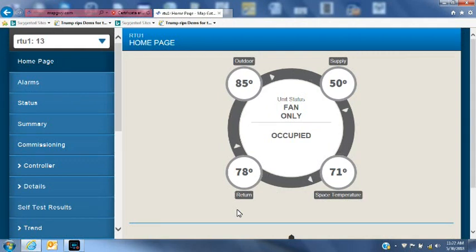In this session, we're going to look at setting up a variable frequency drive, particularly on the split commercial equipment. For the packaged commercial that has a frequency drive, most of the settings should already be set, and you will just have to change the fan speeds or percentage of fan speeds in the setup.